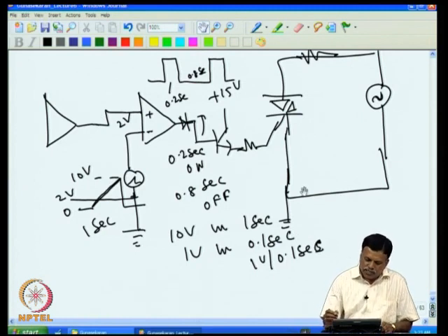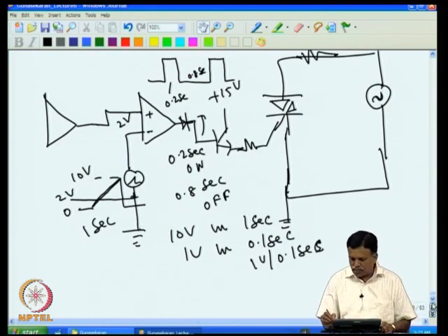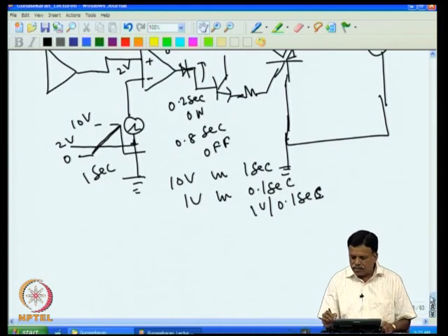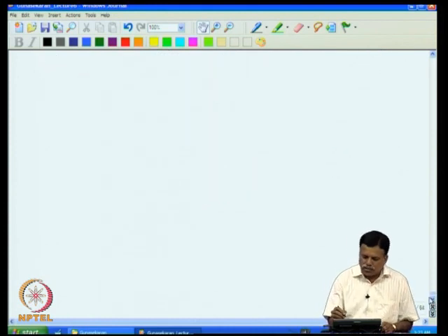This way you can control the resistor. The only drawback of this circuit is that this ground must be equal to this ground, since the current will flow through it. If you want to break this, we can add an opto isolator to this circuit so that there is no shock hazard. So the same thing can be modified like this.